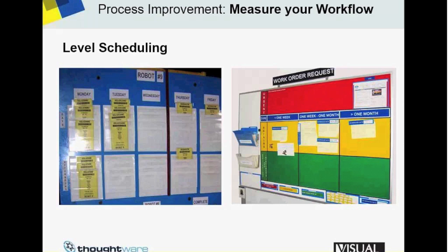In a machine-paced process, the rate may be fixed and the operator hours adjusted to meet the takt. In a labor-paced process, standard work and line balancing templates will determine division of labor and run at rate as labor is flexed to meet takt time. In this particular case, on the left, we have a one-week horizon. We have no finished goods. Our order cards are sized in 2-hour batches, and we're running about 20 SKUs. The components are pulled from an upstream fabrication supermarket, and they're shipped to a downstream supermarket.